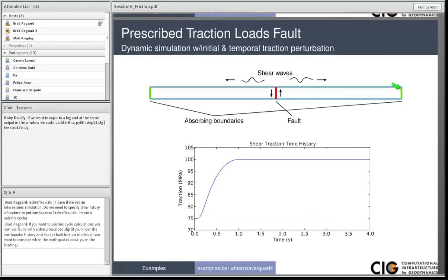very good boundary conditions for normally incident P and S waves. It's only when the waves come in at an angle that the reflection coefficients are slightly smaller. And so as long as our boundaries are far away, the seismic waves tend to come in perpendicular. They also are lower in amplitude, and so we can effectively absorb the waves with the boundary conditions in these dynamic cases. So that's the setup for this dynamic problem.